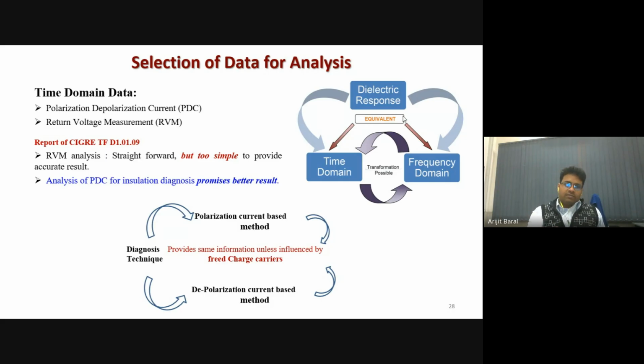Unlike a normal dielectric, which has only one type of dipole present inside the insulation, here we are talking about a very complicated dielectric material which has many types of dipoles present. So the response current will not be a purely exponential decay function, but a monotonically decaying function which can be approximated as a sum of several exponential decay functions, each having unique parameters.